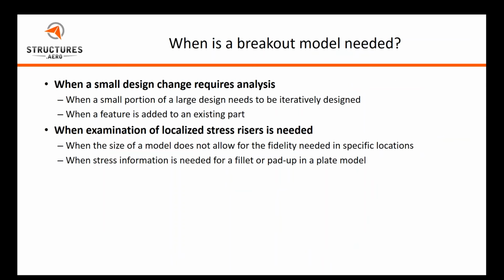All right, when is it needed? Other than that example, a breakout model is needed when a small design change requires analysis. That can be a small portion of a large design that maybe needs to be iteratively designed. You don't want to run your large analysis model over and over again, so you create a breakout model and iterate that. You save a lot of solution computation time. Or when a feature is added to an existing part.